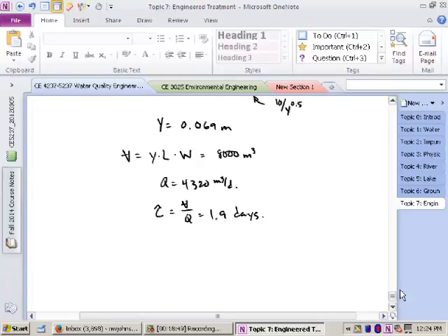What would be some options if you wanted to increase the residence time? Increase the length, so make a bigger wetland. If this is like one cell. Yeah, well, this was just based on a linear flow, and if you have flow going through an area, you have to make something bigger. If you're assuming a plug flow thing going through an area, it doesn't matter how twisty it is. You just have this amount of area that it's going through.